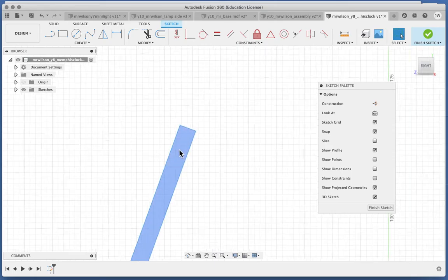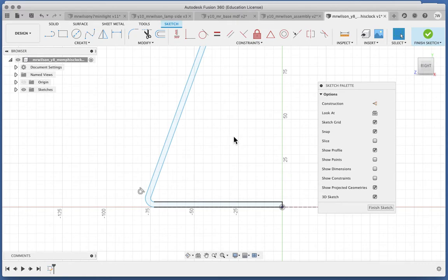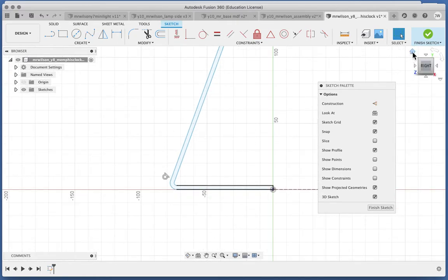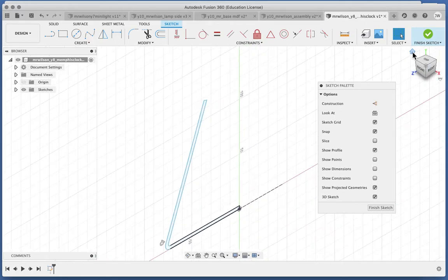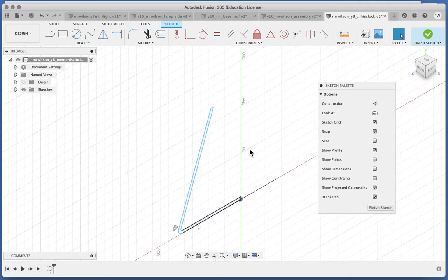And you'll notice as soon as we do that, that it fills with colour, but it can't fill with colour until it's sealed at the ends. I'm then going to go ahead and just put that back in my home view, and I can now extrude that. Just before I extrude it, I'm going to Command S and save, so if my laptop does something funny, I'm not going to lose that 3 or 4 minutes of work.